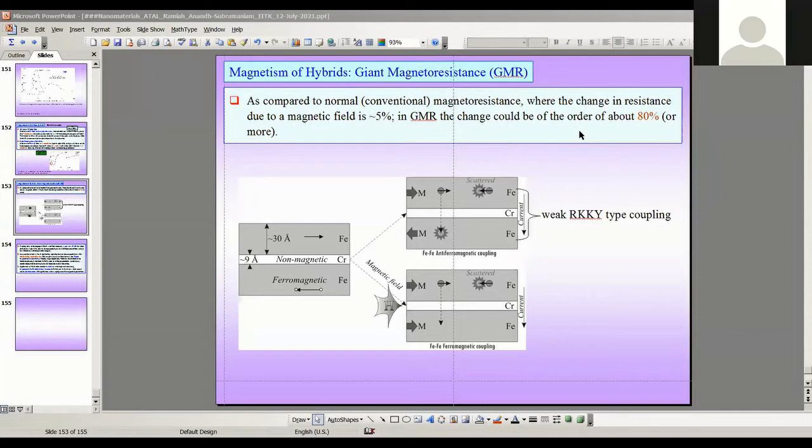So obviously, the Hall-Petch relation is going to break down at some stage. But people have found in some materials that when you go to smaller and smaller sizes, I also told you there is another effect, that you may have something known as the image force coming from free surfaces. You may have dislocation sinks acting at grain boundaries, etc.